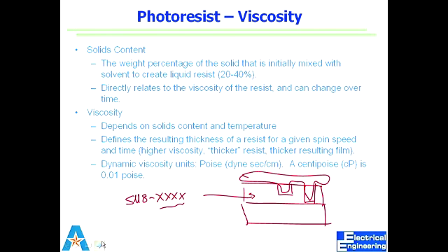And those define what thickness you can get out of this resist. And when I say this is the workhorse of MEMS, we use SU8 to define high aspect ratio features to use it as a mold for PDMS, for other polymers too.